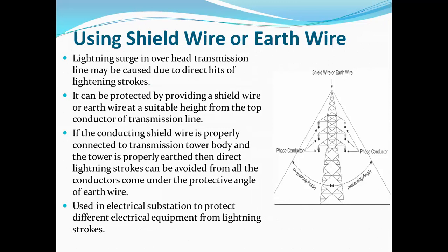Where there are different chances of failure of the insulation, there you can provide insulation which can be easily repairable and replaceable, right? If we provide such insulation, then the cost of repairing and replacing of that line will also decrease. That will protect the system from the over voltages.